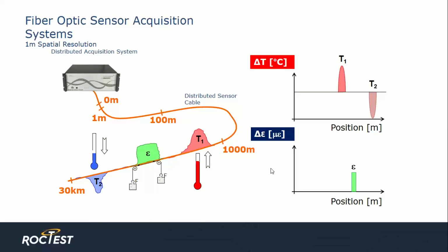A distributed monitoring system is built up on a sensing cable and the interrogator. The interrogator is used to generate the light signal that is injected in the sensor, then to collect the backscatter light and to analyze it. After analyzing the backscatter light, the interrogator is able to show results in terms of temperature and strain, store data, and if necessary, send them anywhere using a standard TCP/IP protocol or other data transfer techniques.